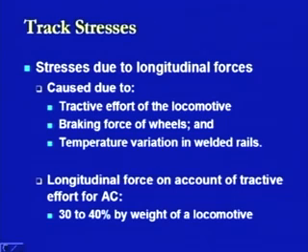And lastly, there is a variation in the temperature, and due to this variation in the temperature, there is some movement, or there are certain stresses which are caused in the rail sections. These are the two things which can happen because of the temperature in any of the rail sections. If there is a certain movement, then it is a sort of creep condition, or if that movement is being resisted by the fastenings which are provided at the top of the sleeper, then that is going to create certain stresses. So we have to look at the different types of stresses which are being caused because of the different factors in the longitudinal direction.